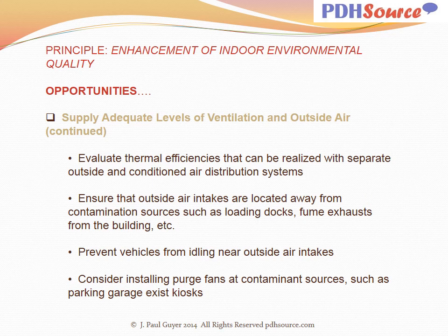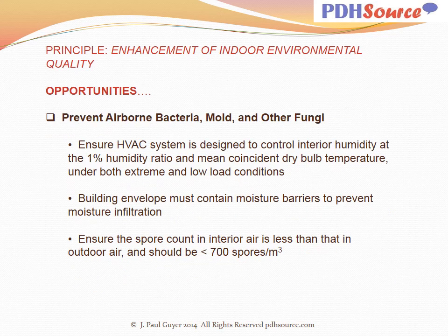Yes, you could save energy by not bringing outside air into the building for ventilation and air quality purposes, but very rapidly the air quality inside the building goes in the tank and gets smelly, unhealthful, humid, and so forth. So you don't want to do that.